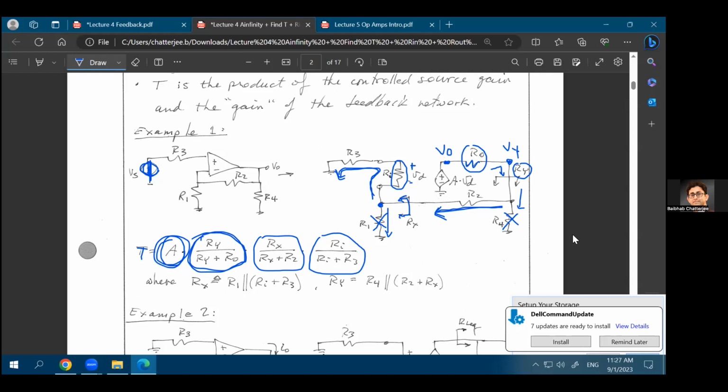Perfect. That's a great way to understand this and explain this. Why are we considering VO and not VY? Because if you change your op-amp, your RO might change. So let's say you analyze a circuit and then you figure out that you could not find, for example, the 3130 op-amp, which is hard to find right now. So most of you are probably buying the 3130 MZ, right? If that op-amp has a slightly different RO, all your analysis will change. And that's why you want to consider the effect of RO as well in the overall analysis when you are doing the loop gain.